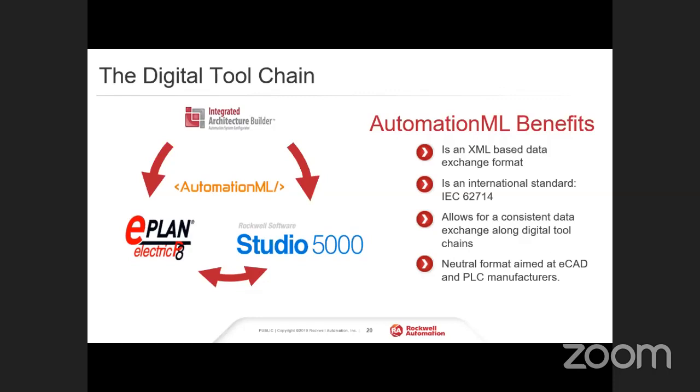That's pretty powerful. So this isn't a Rockwell standard. It's an XML-based exchange format. It's compliant with IEC 62714. It has its own user base, but we've just adopted that, and so has ePlan, to say that here's the way that we expect to serve up data to different pieces of software. And it was in version, I think, 30 and 31 through Architect, but in version 32 of Logix Designer, now you're exchanging information directly from ePlan to Logix Designer. So in version 32, that's the new capability for data exchange.